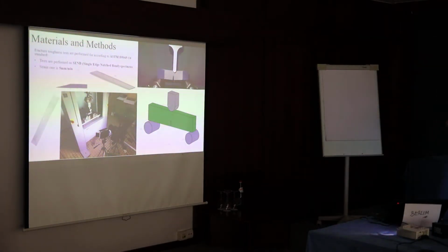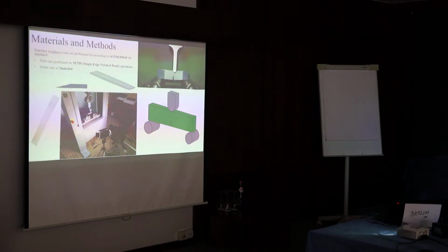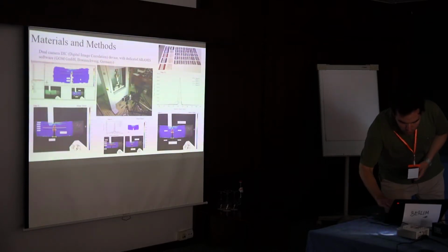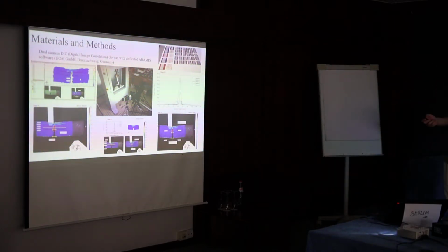Now, we had to create a pre-crack. Of course, we used a hammer. We used a blade and a hammer and made a pre-crack with this razor blade. Here are some dimensions of this blade, and the strain rate of this test was 5 millimeters per minute, according to the standard. As an addition, we used a DIC camera to see the deformations on the front side of the specimen, and as a result, just for this presentation, here is this deformation diagram.